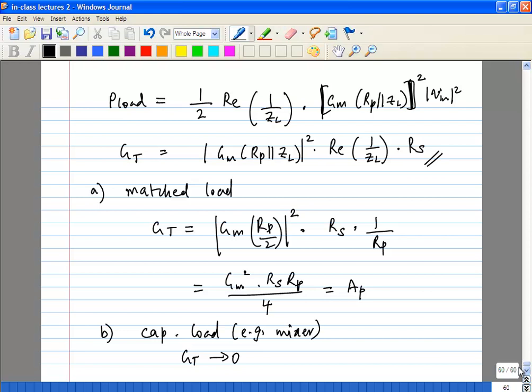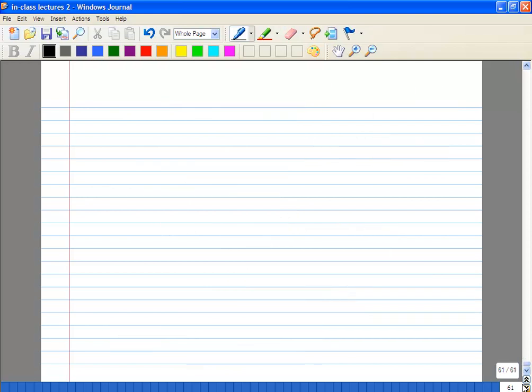Okay, well and good. So now we have found out the gain, power gain, everything. Now, you will notice that when we talked about the design of the LNA so far, we talked about input match, output match, stability, everything. We never talked about power consumption, especially when we derived your minimum noise figure. So we didn't put any bound on your minimum noise figure. If you try to achieve this minimum noise figure, you will find that the amount of power you will have to burn is huge, to hit this number.